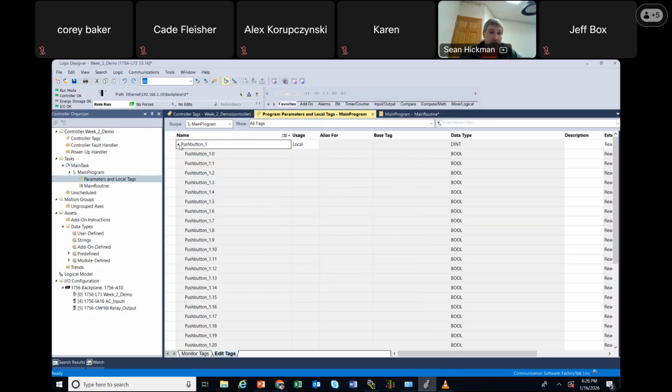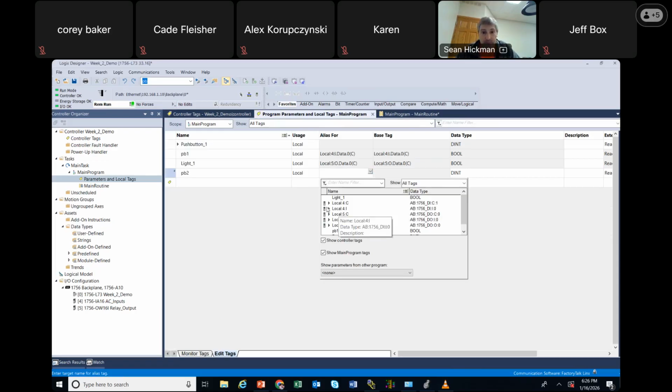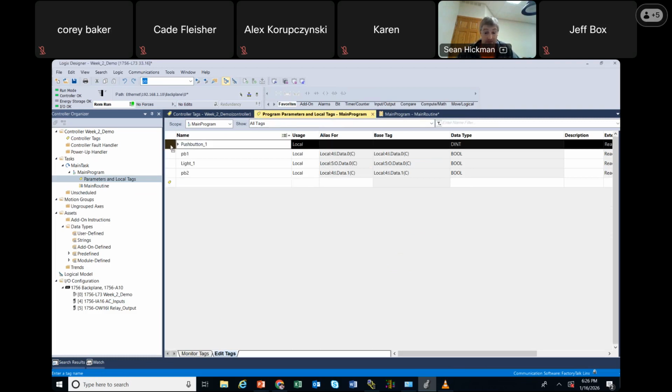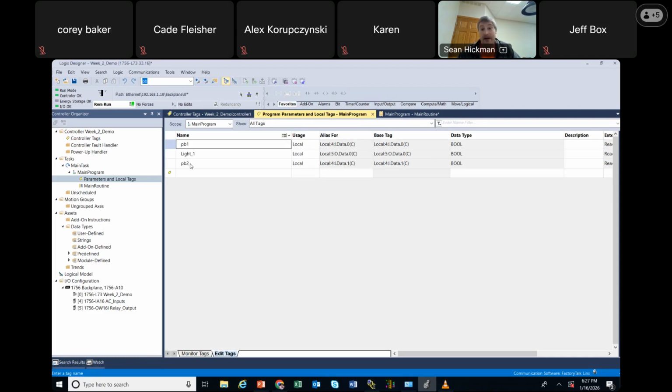You know, like I said, you should be able to come in here, and let me see if I can just do it. PB2 alias for, and that would be an input, and that goes to data. See, you can do it here. That one just got away from me because I kind of started it, but I just made a PB tag here. This thing's just garbage. So if I come up here, I should just delete it, okay? So I made my other tag. I am making these tags online.